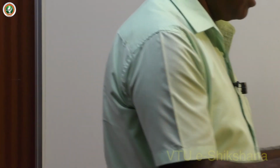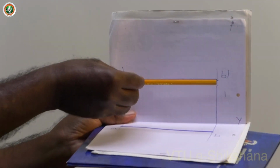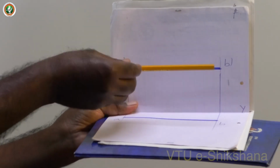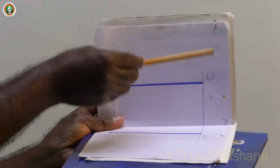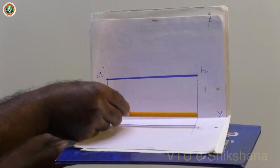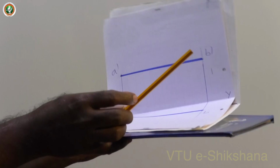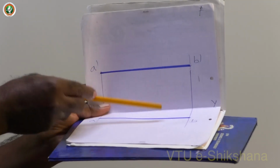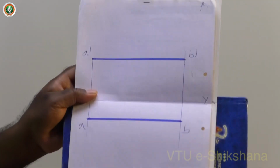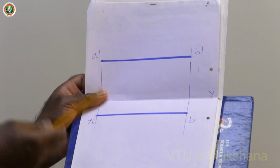Next model is a realistic model. The line is in space. Now the actual line is AB, project it, you will get A dash, B dash, and you project it on HP, you will get AB. Suppose that this is 50 mm above HP and 30 mm in front of VP. So what about the distance of the front view above the XY line? That is 50 mm. Then this one is 30 mm. Now you rotate, you will get the top view and front view. This is A dash, B dash, this is AB. So this is how you can understand the straight line concept very easily using these models.